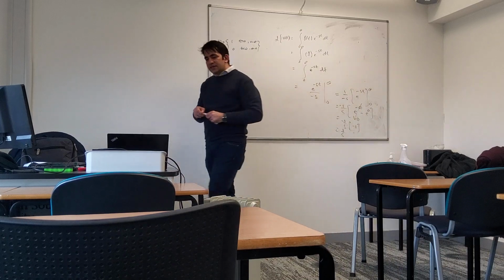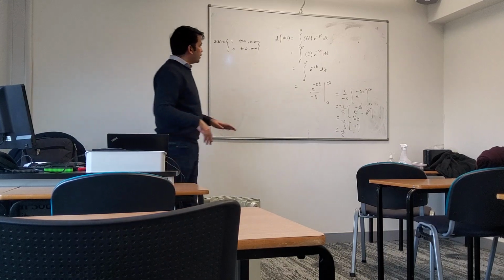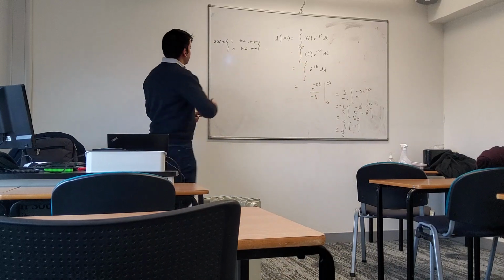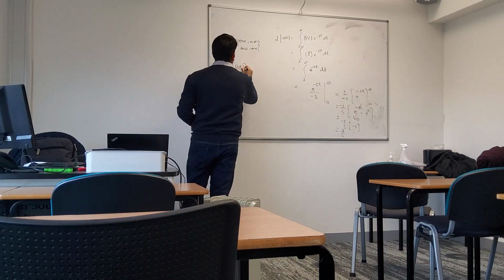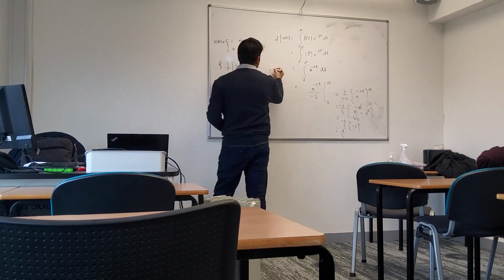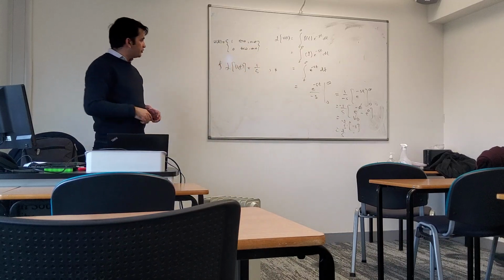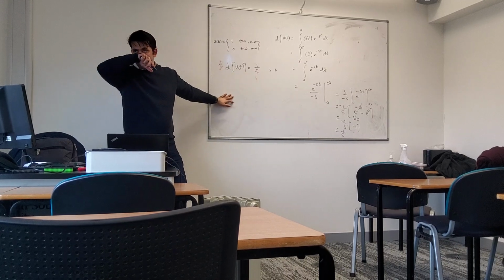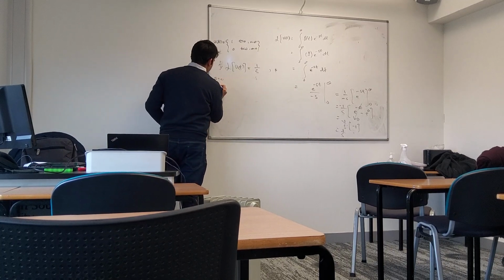So it means that solving for the unit step function was much easier in the Laplace domain than it was in the Fourier domain. So the Laplace transform of u of t is equal to 1 by s. Now for s we can put different values. Okay, now how are we going to analyze it? S is the frequency domain, right? We need to analyze this function. So let's analyze it. We can put s equals 0, s equals 1, and s equals infinity.